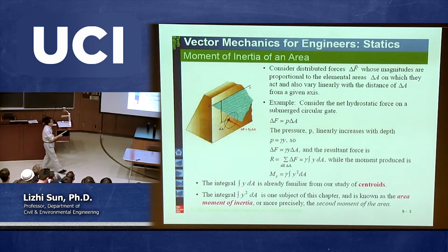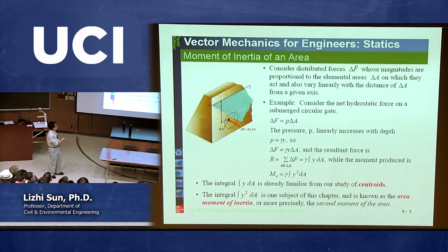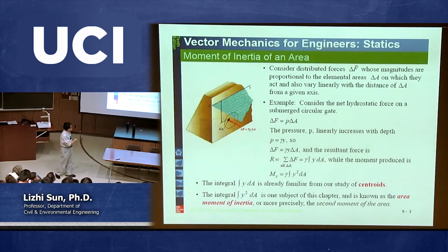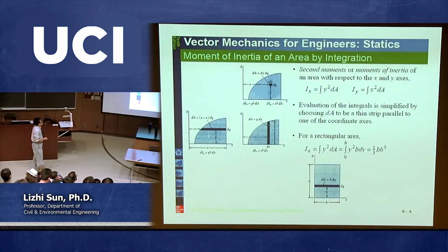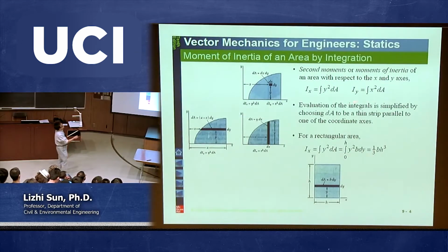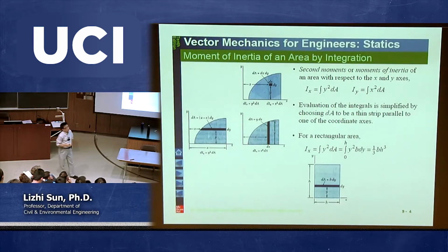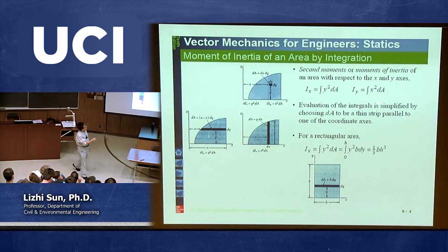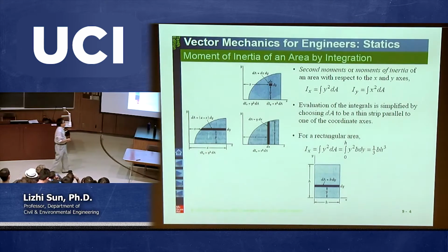moment of inertia. So this one, in fact, is a moment of inertia, which by definition is the integration of y squared dA, which is the moment of inertia with respect to the x-axis. Then, of course, correspondingly, if you want to talk about the integration of x squared times dA, that is also called the moment of inertia with respect to the y-axis. Okay, so these two are the fundamental definitions of moments of inertia.